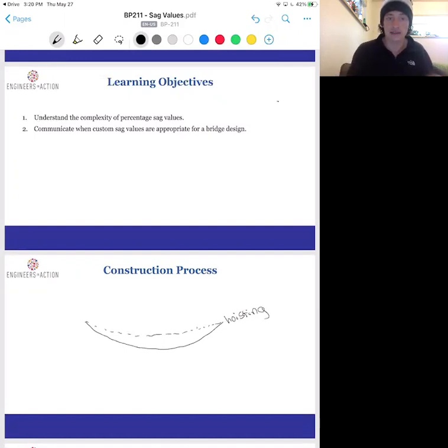We then predict that the dead load, decking, suspenders, etc., discussed earlier, will bring us down to the design Sag shown. I'll show here in red. And then the full dead and live load together will bring us no lower than the live load Sag, I'll show here in green. So I'll hit that live load, and the red was dead load. And these are our various Sag values.